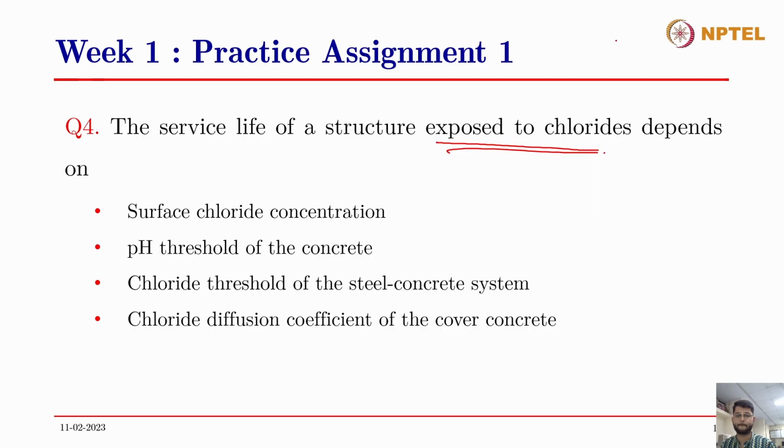Yes. Chloride diffusion coefficient is a factor because the cover concrete area is very important. Then chloride threshold has to be a factor because that is related with the time and chloride concentration also. Then surface chloride concentration also matters because if there are more chlorides on the surface, then obviously there will be more intrusion of chlorides. So answers are three.